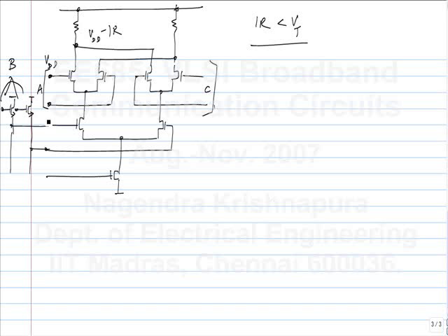So if you level shift everything, of course everything will work the same. Then you can increase the swing. But with present day logic voltages of 1.8 volts and less, typically you don't have that. You have only one set of followers. Now there are other ways of level shifting. You don't have to use voltage followers, especially because this is an over design. We wanted a common mode difference between A and B equal to VD sat, but this will provide a difference equal to VGS. So you can use some other scheme to level shift it by something less. And also we'll see a bunch of cases where A and C come out of some logic signals, whereas B comes from some other circuit. So you can adjust the common mode of that circuit independently of A and C.